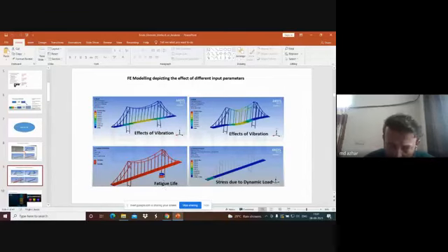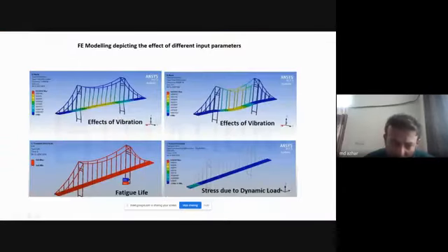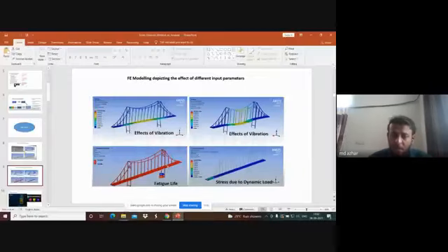Fine, you can see the fatigue life. Here the figure is a little bit small on the monitor, but you can see this particular structure is minimum and this particular structure is maximum. So the engineer will get to know that this particular structure, due to the vibration and the various load cycles which are happening, can fail earlier. So the engineer will either perform maintenance for it, or they can replace the existing material with material which has a higher fatigue life. All these things can be done.